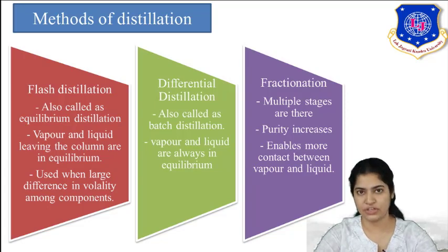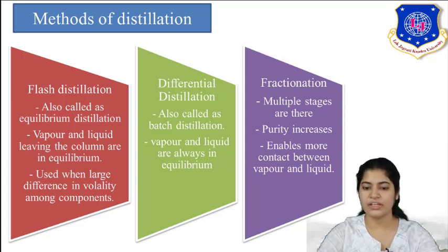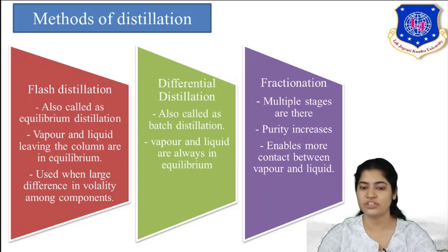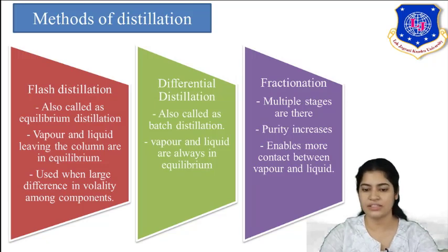The last one is fractionation. What is fractionation? It is also called multiple stage distillation. Flash distillation and differential distillation can be taken as single stage distillation, but in fractionation multiple stages are there. Multiple plates are arranged in this column, and each plate behaves as a single stage.